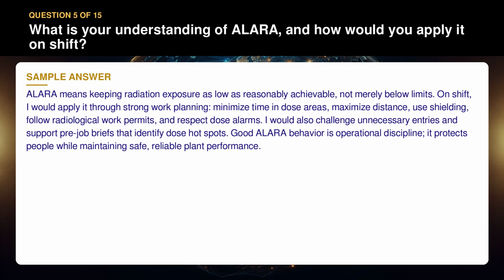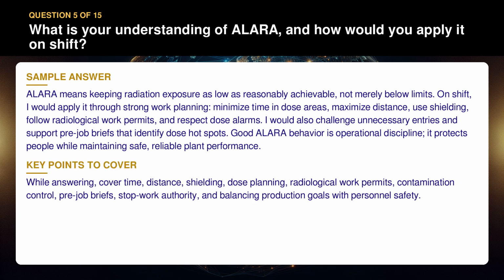I would also challenge unnecessary entries and support pre-job briefs that identify dose hotspots. Good ALARA behavior is operational discipline. It protects people while maintaining safe, reliable plant performance. While answering, cover time, distance, shielding, dose planning, radiological work permits, contamination control, pre-job briefs, stop work authority, and balancing production goals with personnel safety.